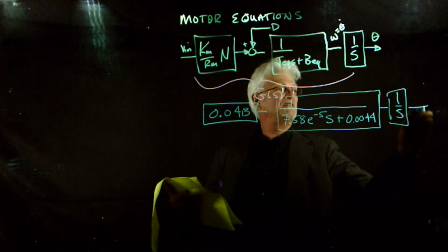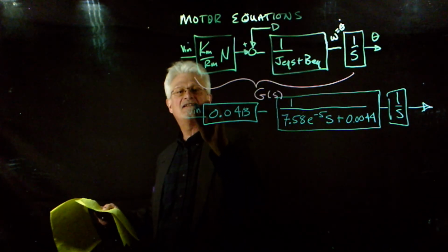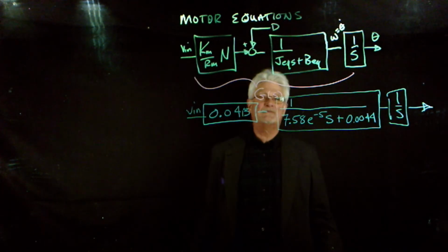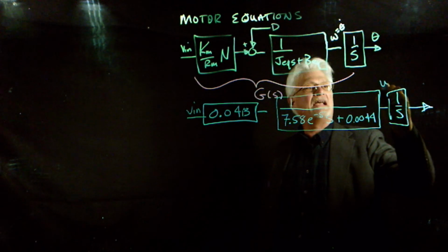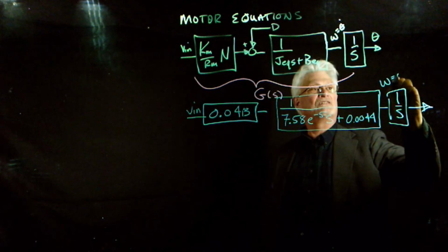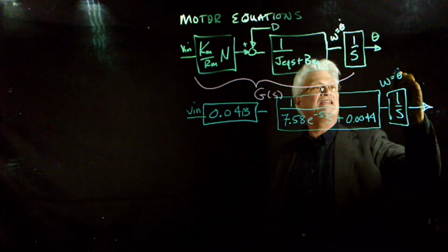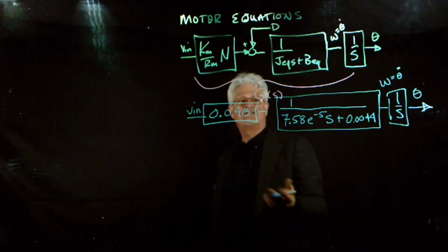So if I just put numbers into it, that's all fine. If you put a voltage to the motor, then the angular velocity omega gets to be a constant. That's a first order thing. Omega equals theta dot, and then theta just keeps going and going and going. And what we're trying to do is control the motor.